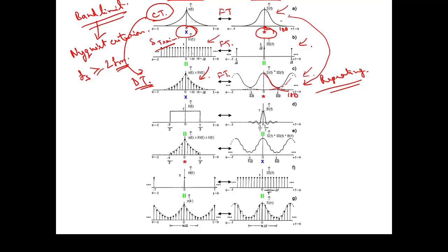So frequency components above this fm would also be present. To make our system capable of handling whatever signal component you are trying to analyze, we have to band limit the signal such that this Nyquist criterion is being followed.